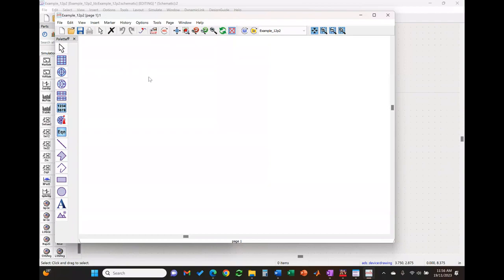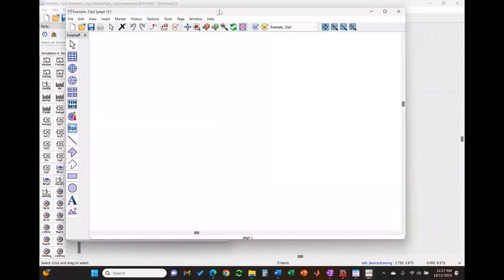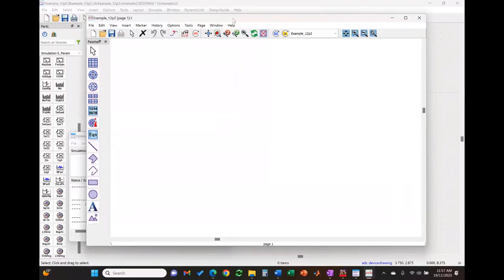Okay, so again, we have this empty space. Now, remember, we can show the values. Remember, when we talk about mu and when we talk about k, we need to show their values. Now, another thing that we also need to calculate, but ADS doesn't do this for us, is delta, which is necessary for the K-delta test. Now, how can I use ADS to calculate delta?